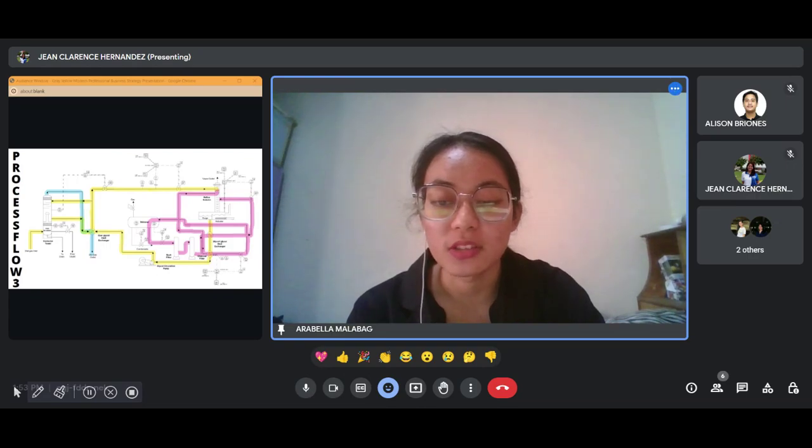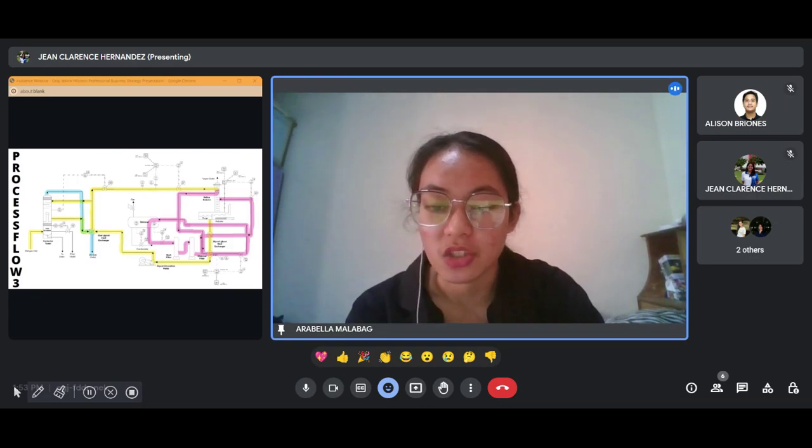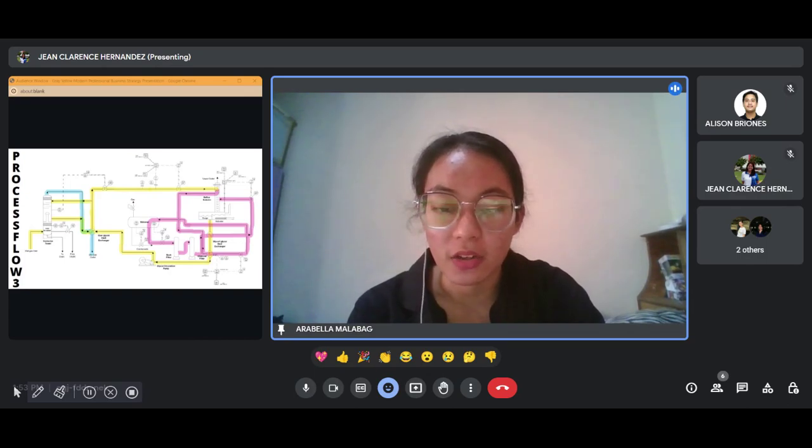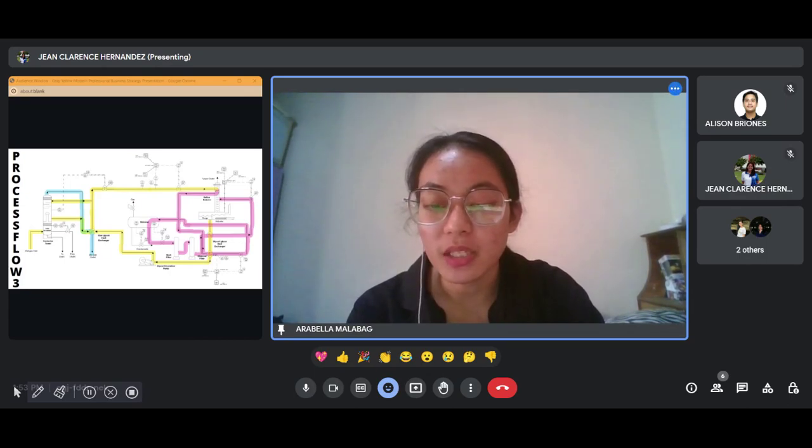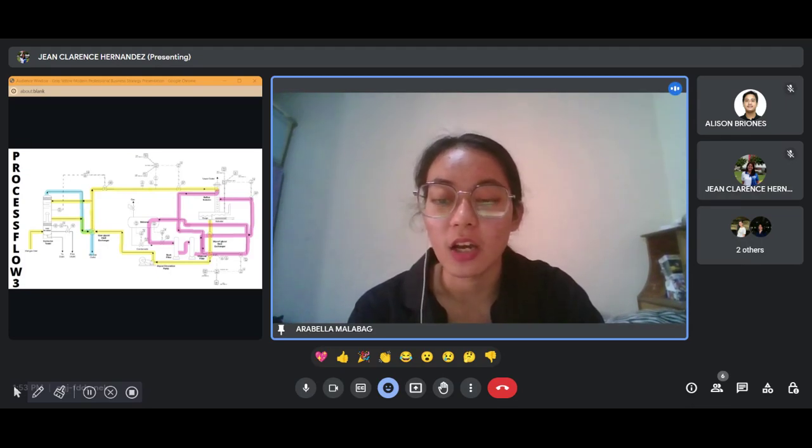and the dry gas will now proceed to the gas glycol heat exchanger, where the dry gas will exchange heat with the rich glycol, so the dry gas will be cooled before it goes out of the dry gas outlet. The dry gas is the main output of this process, and the process repeats until the desired output is achieved. Next slide, please.